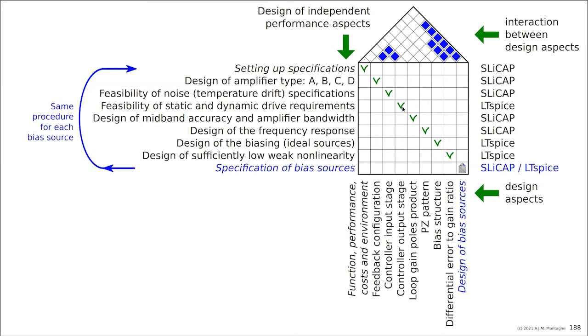We need a passive element that behaves as a current source. If it is passive, then in the origin it will always have a resistive behavior, and then the VI characteristic will saturate to some kind of constant current characteristic. So there will be drive requirements for the bias sources.